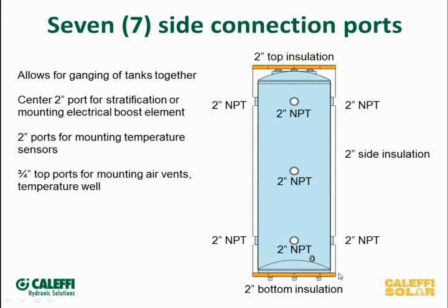And we're giving you a tank available in the 58 or 119-gallon version. And what we've done is we put in seven 2-inch ports on different sides of the tank. So you have 2 directly across from one another, 180, and then at 90 degrees from that, we've got 3 additional 2-inch ports. So you've got 7 ports. So now that makes it really easy to put a heat pump right into this side and then take your load off the opposite side here. It also serves as a little bit of a hydro separator. I mean, it really is a supersized hydro separator, and by giving it a dome top like that, you can put an air vent in that center port there and get some pretty good air removal from this.